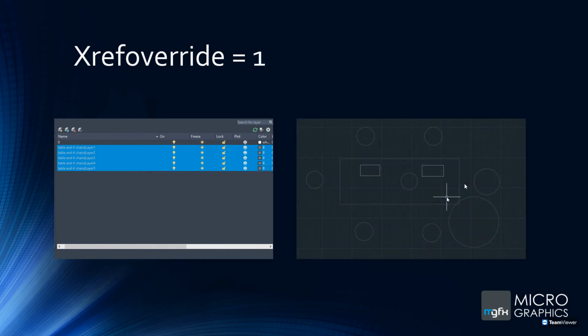So if you want it to be all the same color and disregard, even if it's by layer or by color, or the line weight is by layer, or you've actually specified a line weight in your properties, it will then go and change everything to do that. It actually ignores that and will choose everything to be gray over there.